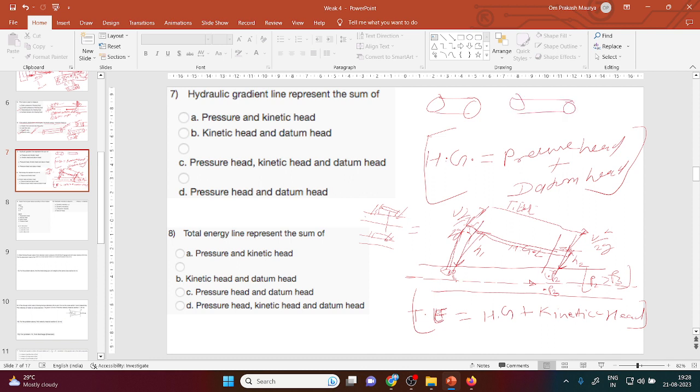The friction of the stainless pipe is F1 and of the copper pipe F2. The cross section, pressure, and velocities are the same for both, but the hydraulic gradient line will be different due to the friction only. Yes, sir, the difference will be due to the friction.